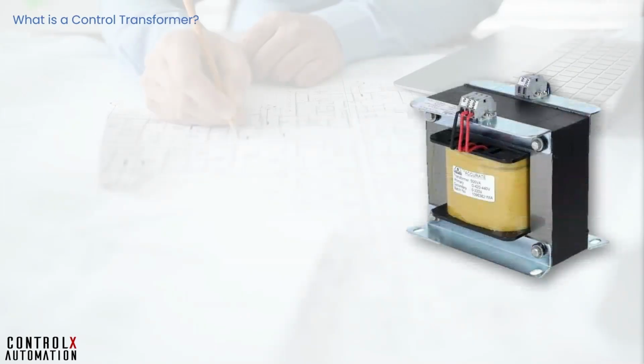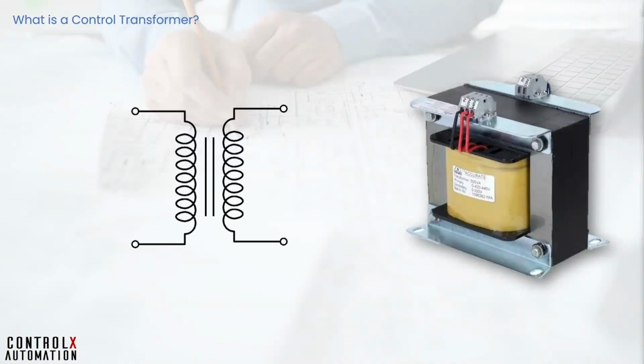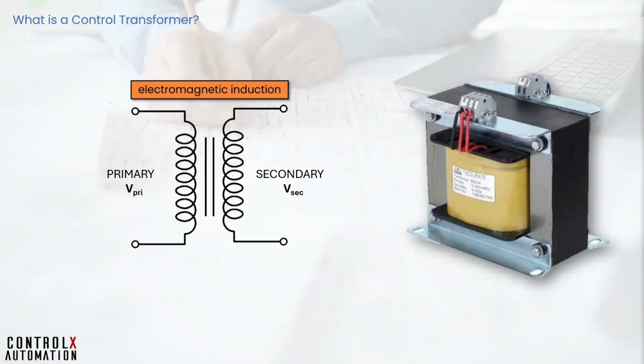Let's start with the basics. What is a control transformer? A control transformer, also called a machine tool transformer or industrial control transformer, is a dry type single-phase or three-phase transformer specifically engineered to supply a stable voltage source to AC control circuits in industrial machinery, motor control centers, and control panels. Its electrical symbol looks like this. Here I'm showing you a single-phase transformer, which means it takes a single-phase voltage applied on the primary and transforms it to a different voltage on the secondary through the principle of electromagnetic induction.